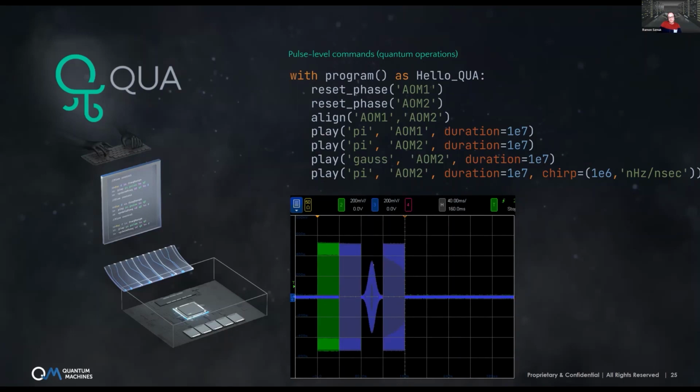I replaced this ramp with a Gaussian waveform. For this Gaussian waveform, I gave the samples for, I think, a 40 nanosecond envelope, but now I'm stretching this to 40 million nanoseconds, and it's on the fly performing this third order Lagrange interpolation and outputting a Gaussian which is 40 milliseconds long.